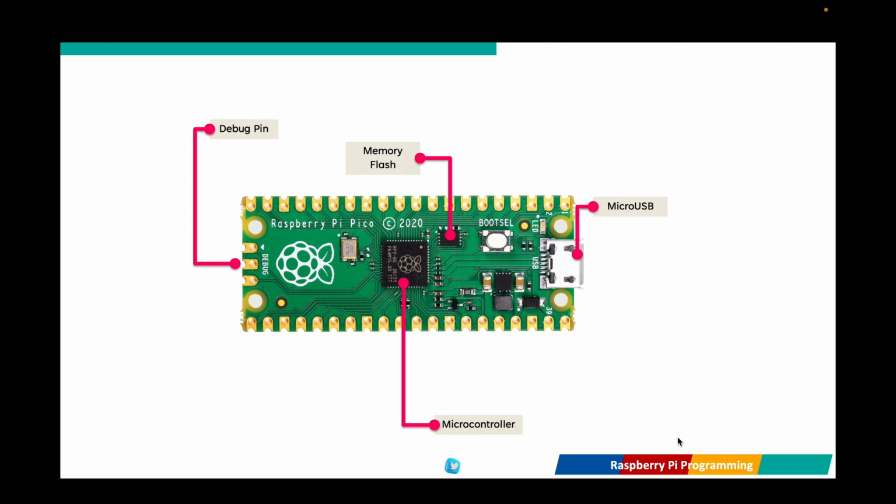A unique feature of the Pico is its programmable I/O (PIO) blocks, which allow custom protocols and high-speed data transfer without using the main processor. This is especially useful for handling LED matrices, signal processing, or even VGA output.